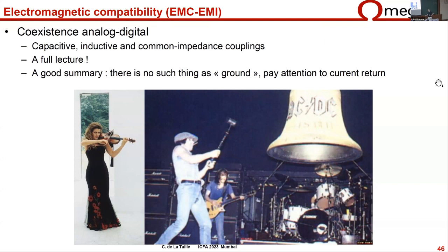When you go to calorimetry, for example, let's take the high granularity calorimeter, which is something which we know here. The MIP is the same. The thickness of the silicon is the same, and so you get the same amount of femtocoulombs. But now the pixels in the calorimeter are 1 square centimeter instead of 50 micron by 50 micron. And so the sensor capacitance is now 50 picofarad instead of 50 femtofarads, which means that on the input you are now sensitive instead of 10 millivolts to something like 10 microvolts. And so the digital noise is very quickly going to make hundreds of microvolts on the ground and everywhere. This is something that is very difficult to fight.